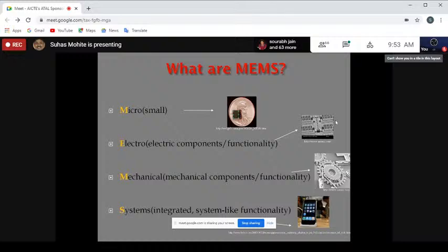So this is something that has to be borne in mind by mechanical engineers, that conventionally we use various mechanical manufacturing processes. However, MEMS devices essentially make use of additive and subtractive manufacturing and the processes that go into manufacturing of electronic circuits. So IC fabrication technology or the processes are being used by the MEMS fraternity. So this is another important thing.